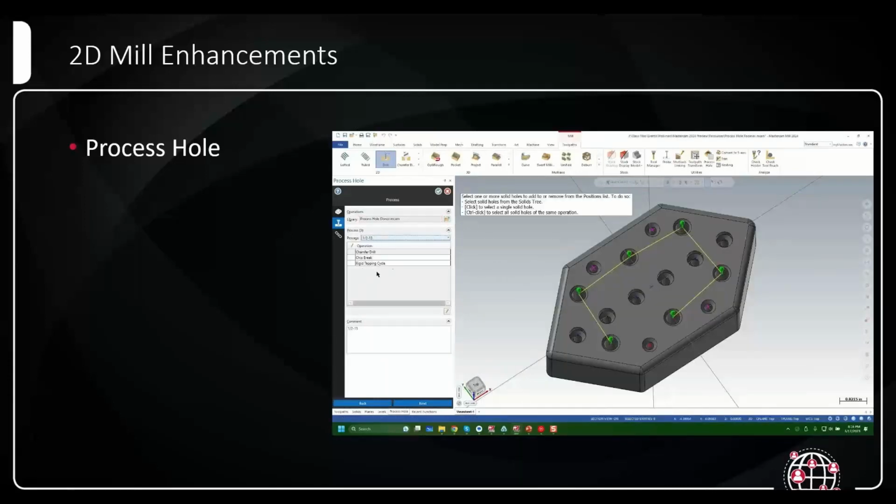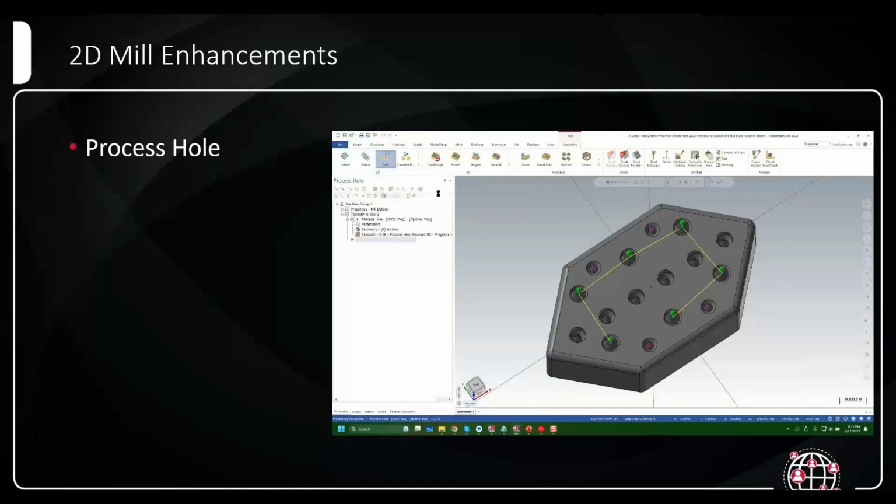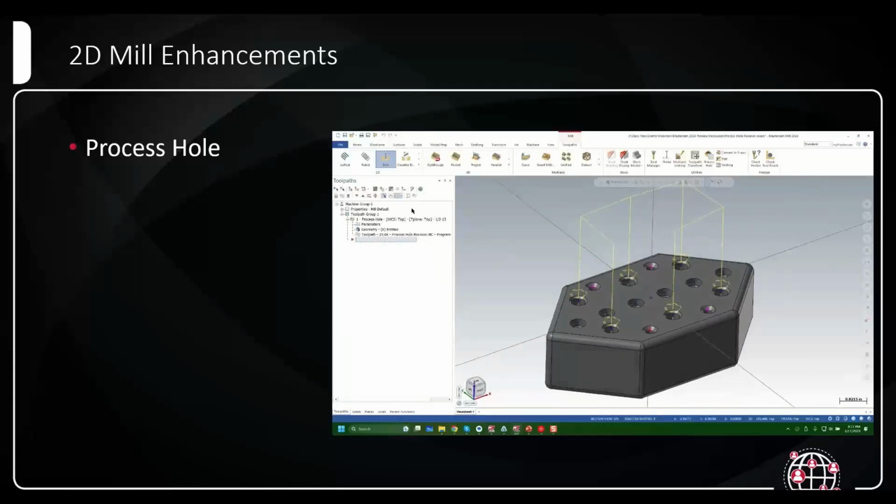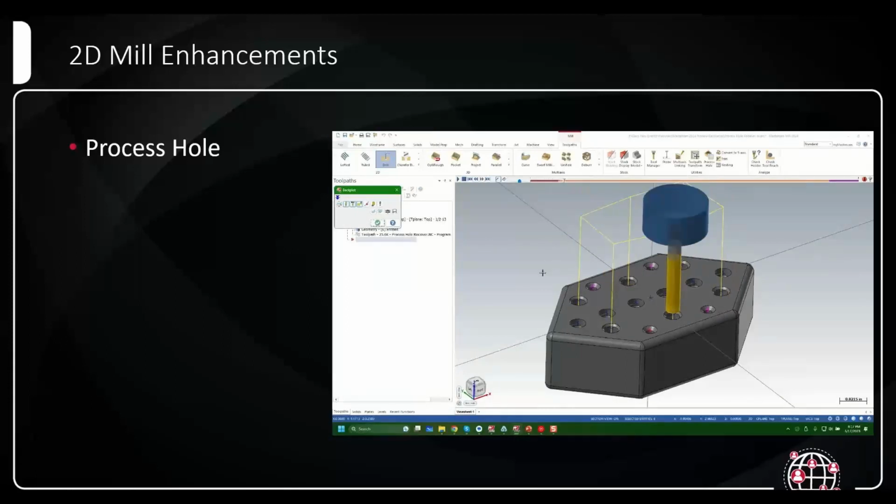But essentially it's identified, okay, in this other part file, this is the same size hole as what you did for the tap drilling routine. So in that second page, I kind of blew through it. It showed the spot drill I did, the tap drill, and the tapping. I can control the clearance plane for this particular part. The depths are going to change automatically. You can see it's already doing the tap drill there. And then it goes back to do the taps.